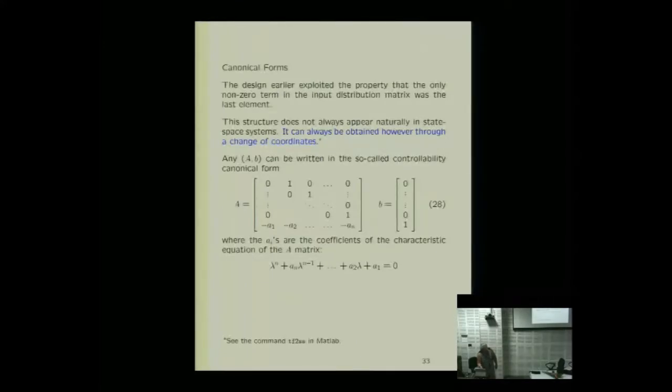So if we look at a very classical canonical form as in 28, which we introduced to our students, it's in the form we want. It has the control input acting in the channel, the single final channel, and then it has n minus m channels where the control input doesn't act. And thus it becomes very, very straightforward to write down a sliding mode control paradigm for systems in this form. Indeed, for nonlinear canonical forms of that type, we can do the same thing as well.